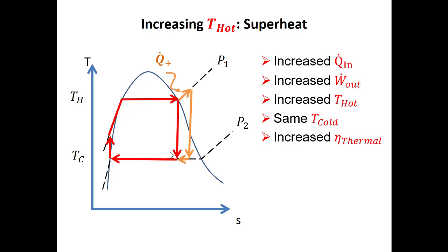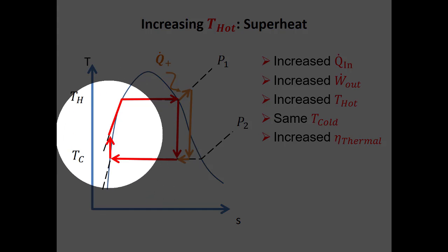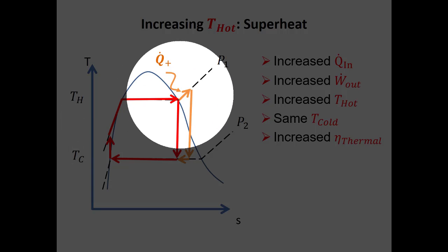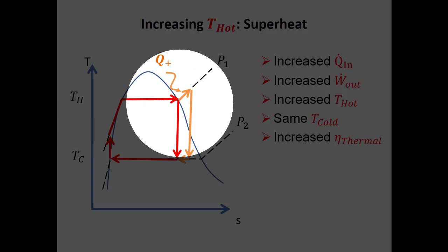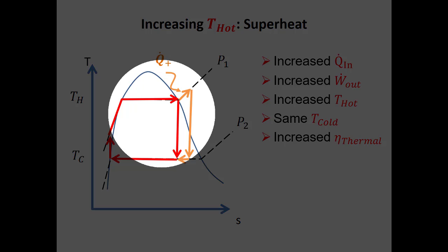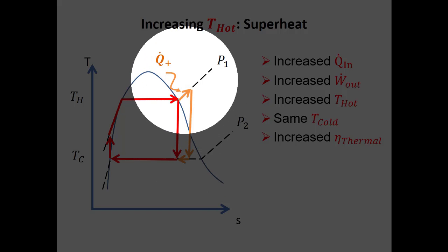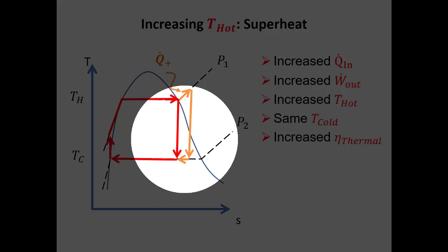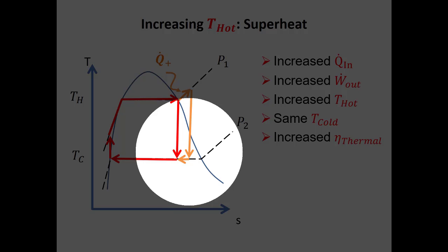But we increase the enthalpy of this saturated vapor more quickly, I think, than when we're increasing the enthalpy of this liquid, right? Because it's already boiled, the liquid, right? So the temperature kind of runs away as you heat up steam. So if we do this, we're adding heat, but we're also getting more power out, right? So here, we're traveling a longer distance along our isentropic turbine in this example.